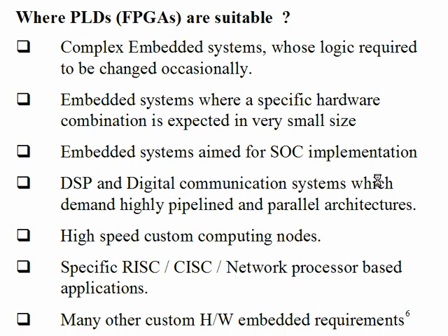My idea is, let's say I have a microcontroller, I have a big RAM which is outside, and I have maybe one analog to digital converter, or some other parts on the board. I have taken a PCB and put all these things together. So the interface between all these chips is coming up on the board, not on silicon. Got the point? The other approach is what? Take a single chip which can have a microcontroller core inside, maybe the RAM, flash, many things inside, and everything you are doing on silicon. So you have many advantages when you are able to do everything on silicon rather than coming out of the silicon and running on the PCB.